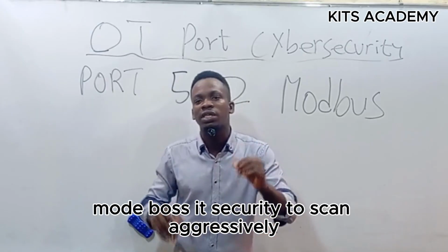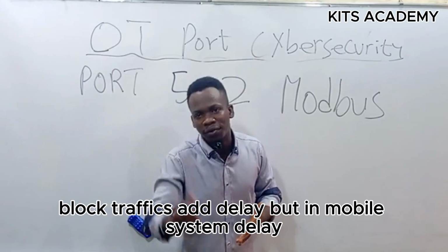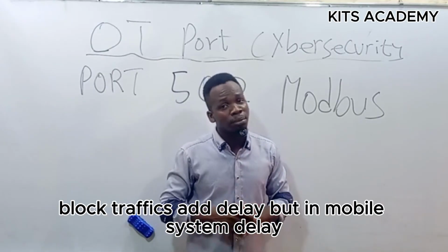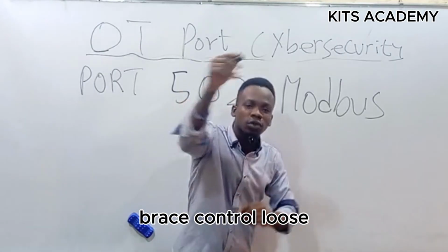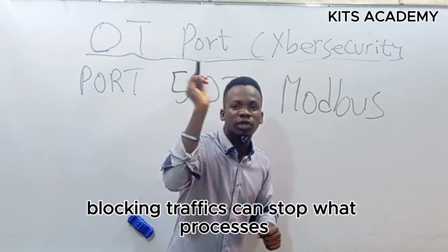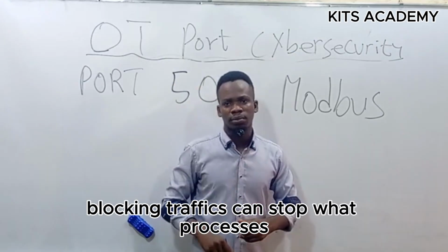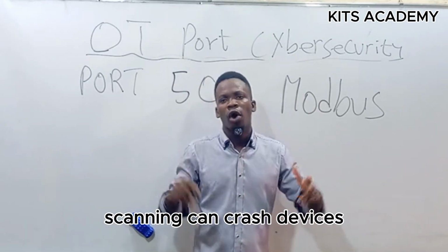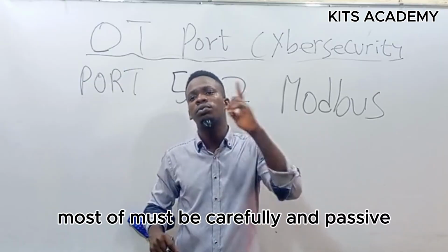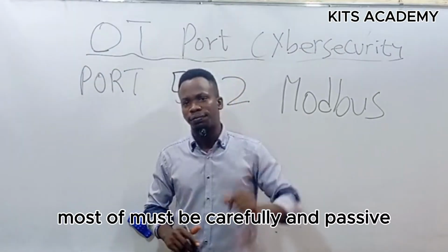Why do IT security tools struggle with Modbus? IT security tools scan aggressively, block traffic, and add delay, but in an operational system, there are delay-based control loops. Blocking traffic can stop processes. Scanning can crash devices. Operational technology security must be careful and passive.